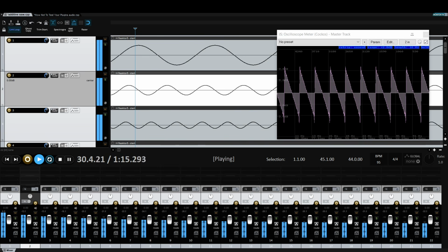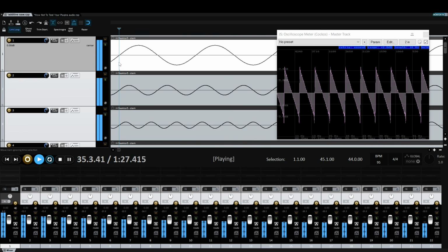That's not our concern today, however. Instead, we're trying to explain the increase in peak levels caused by phase shift. Now, all these sine waves are currently neatly aligned, starting at 0 phase, and they stay locked in relative phase because they're all at integer multiples of the same frequency. That's why they add up to create a neat, orderly sawtooth shape.